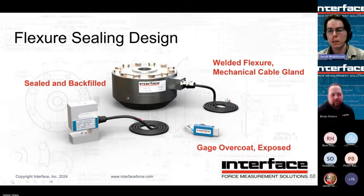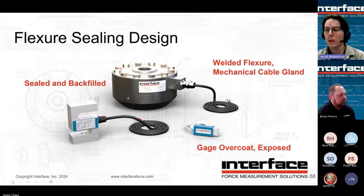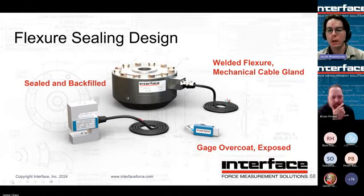You see here on the left, SSM. That stands for like a sealed S-style load cell. And it basically has a cable gland on one side, and then that internal cavity where we have the strain gauges, we kind of backfill that with a gel potting compound, and that helps seal the bridge from any moisture ingression.